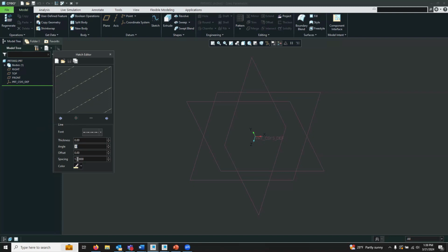What I do want to show is we have the ability to create additional lines. So let's say offset 3, angle 45, and add. We'll notice that now we have both of these added. Actually, we have 3 because I added one behind the original as well in gray. We can change our colors, customize this however we would like, and save.